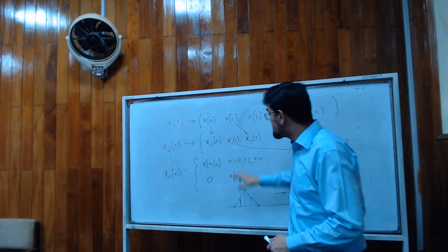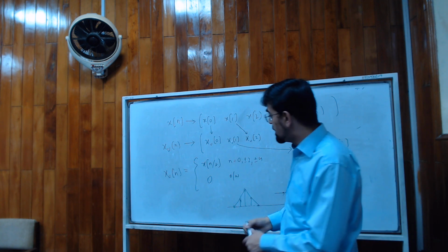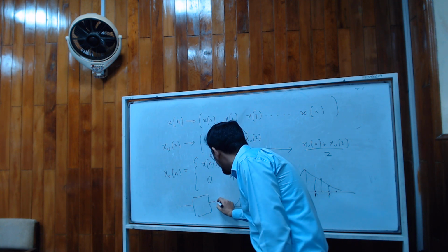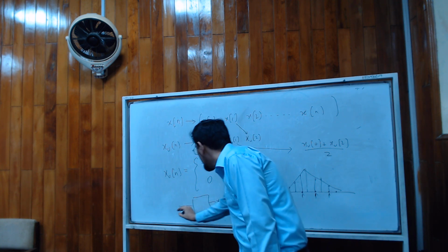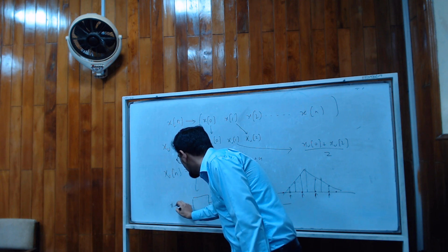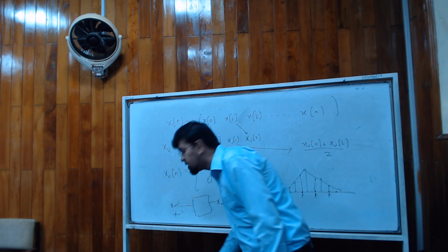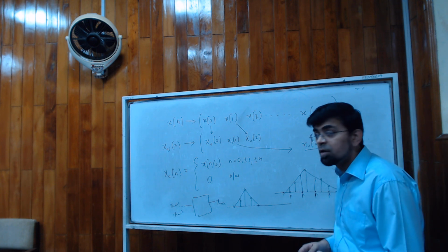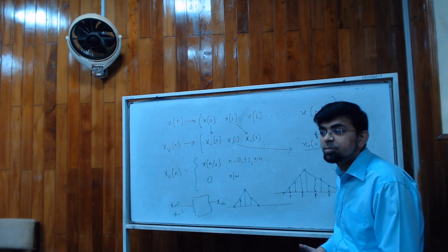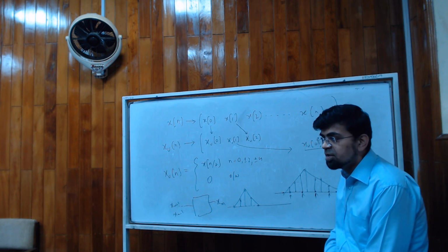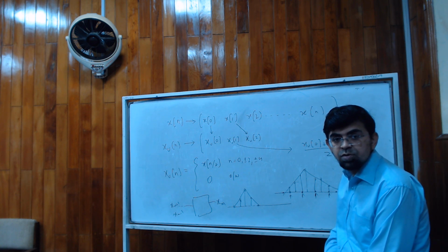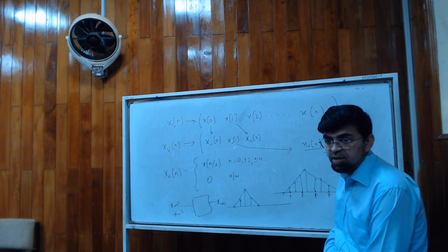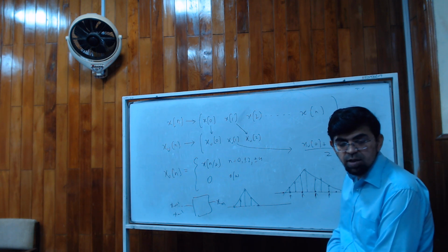I'm saying this system that generates this value looks like this. It gives you the middle value, let's call that xm. It takes in one value before that and one value after that, and gives you a value there. So it is depending on future values, so it's a non-causal system. So if you are going to do upsampling like this, you will need to buffer some values.